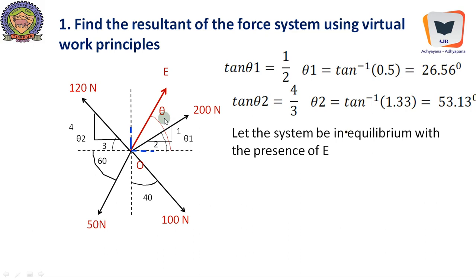This equilibrant is inclined at an angle of theta, and we will give the displacements over here: positive virtual displacement dx to the right of O. So O dash will be over here horizontally, and O dash will be there vertically up with a small virtual displacement of del y vertically. So we have presumed positive virtual displacements horizontally and vertically, and we will resolve all the forces into horizontal components and vertical components and multiply with this